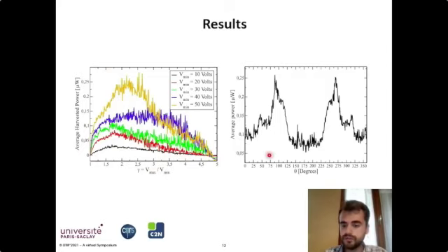And here on the right, we see different orientations of the device. So we go from 0, which is when gravity is parallel to the device, and we rotate it, and we see how this affects the power output. So we see we get a maximum of 250 nanowatts where the capsule is perpendicular to gravity, and when it's parallel, we have 0.1 microwatts. So we lose about half of the power when we're facing gravity.